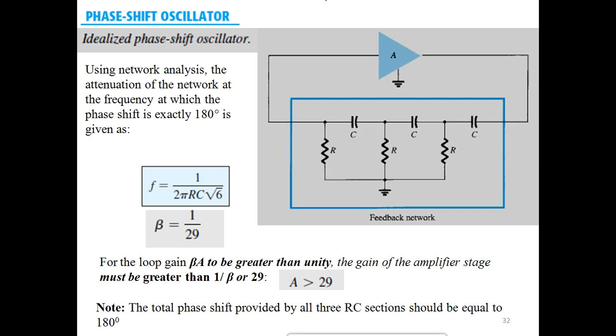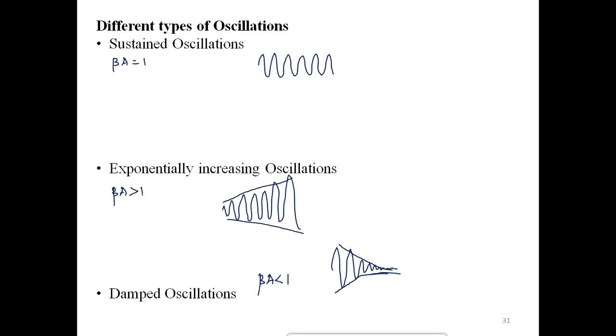Now before we proceed to practical oscillators, in the last class I had also mentioned the nature of the feedback circuit. If we consider this to be an amplifier and the second block to be the feedback network, the concept of an oscillator is very simple. Without any input you will be getting an output signal, provided the Barkhausen criteria are satisfied. So at the output side you should have the output V0.